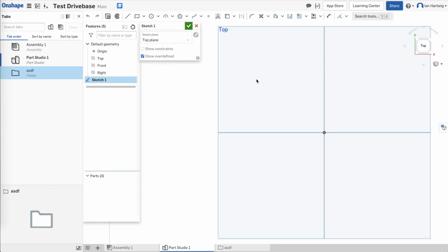To start off with, we know that we want to make a bunch of holes. So let's start with the center point circle. If you hit the arrow, you can get different kinds, but the default one is this center point circle. Sorry, I deselected it. This tool is active when it's selected blue over here. If you click it again, or if you hit escape, it will deactivate.